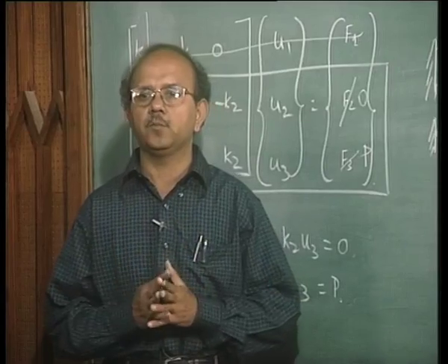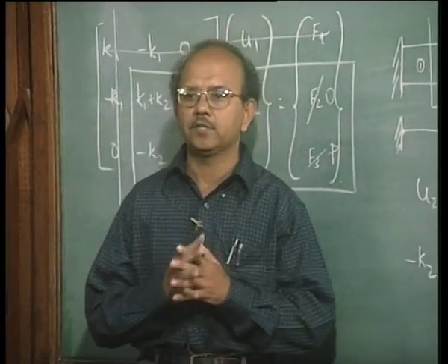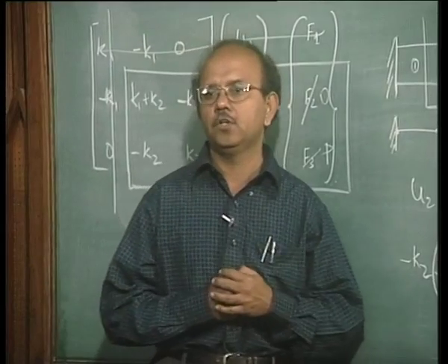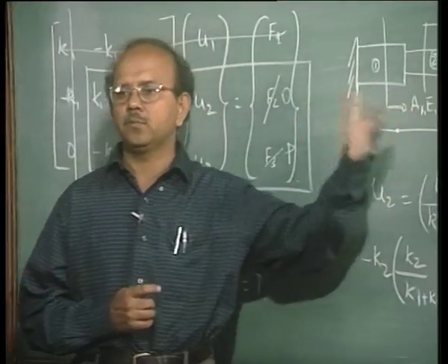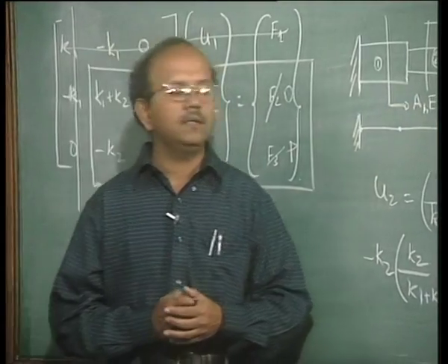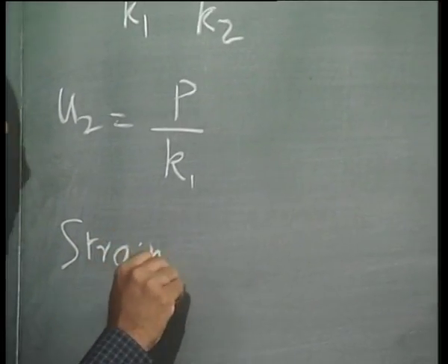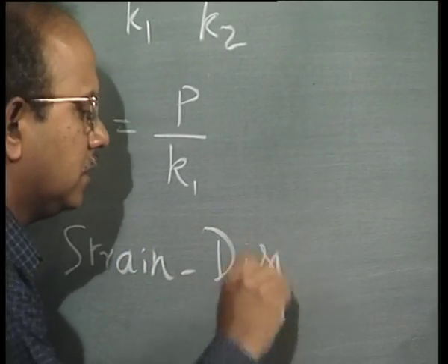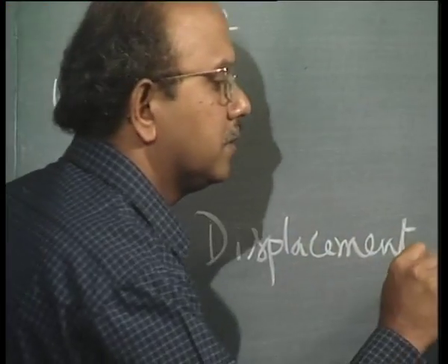Once I know the displacement, what is my next step? I have to determine the strains, because ultimately I am interested in stress. So we solve these equations and determine displacement. Then we go to strain through what is called the strain displacement relationship.